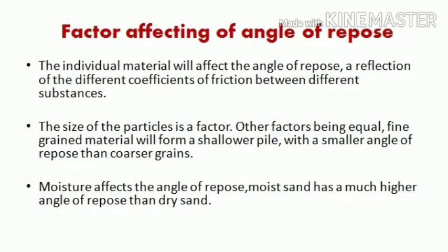Now the factors affecting the angle of repose. There are many factors affecting the angle of repose. It varies from material to material. The individual material can affect the angle of repose, reflecting the different coefficients of friction between different substances. Next, the size of the particles may affect the angle of repose.